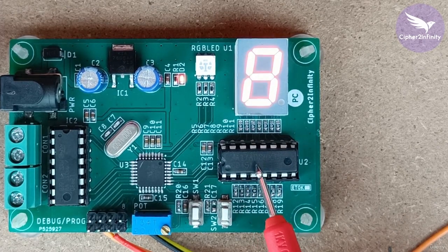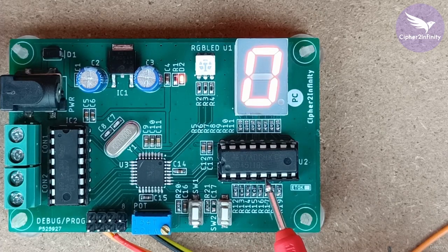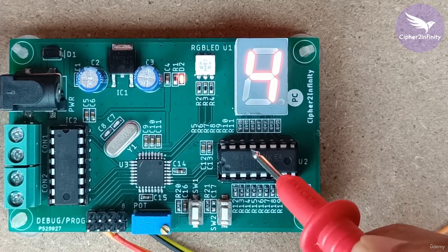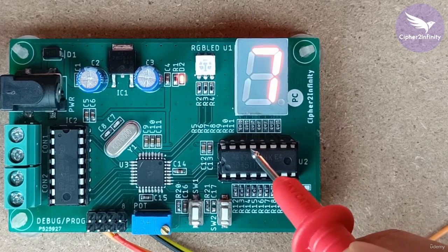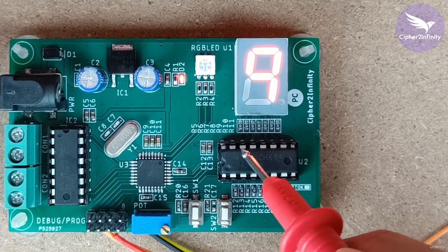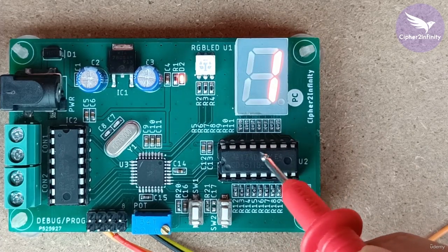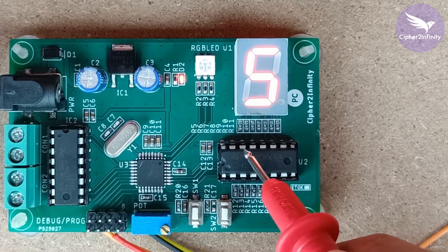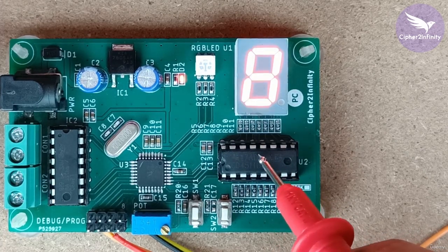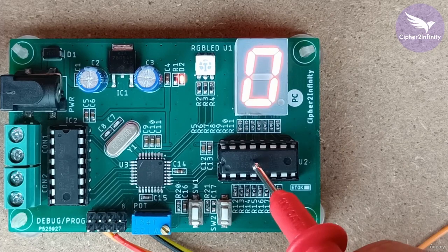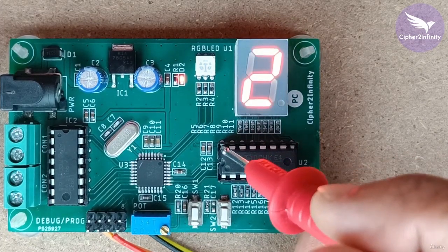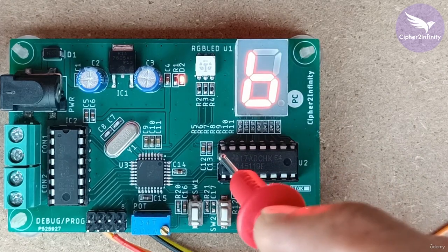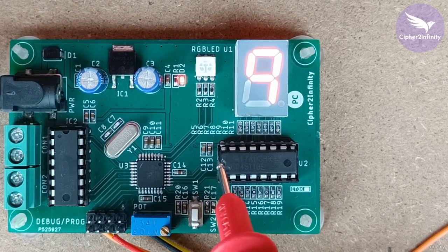Once you are sure that you are getting the voltage on the input side, then you have to go to the output side, and you have to check whether you're getting the appropriate voltage on the small abcdefgh pins of the 7-segment display driver IC. Now, if you are not getting the appropriate voltage, or if the voltage is not produced by this particular IC, it means that you have to check the power pin of this IC, okay? You have to check whether the 5 volt is available on the power pin or not.